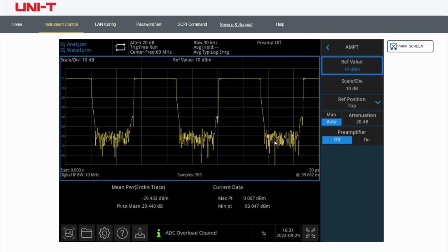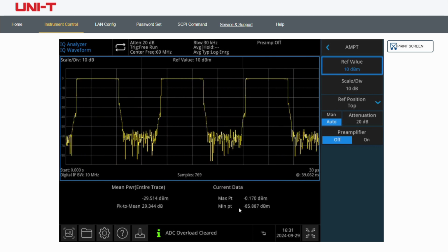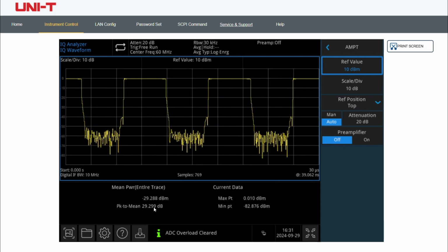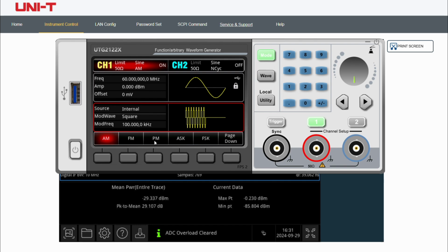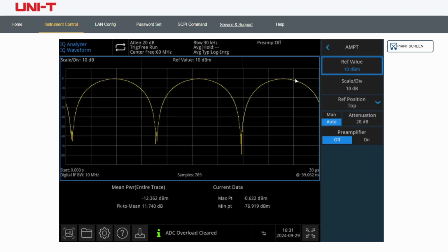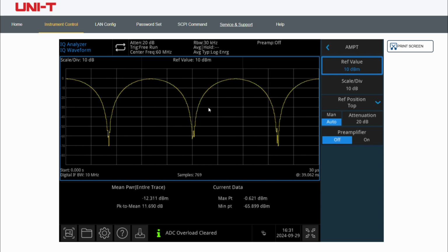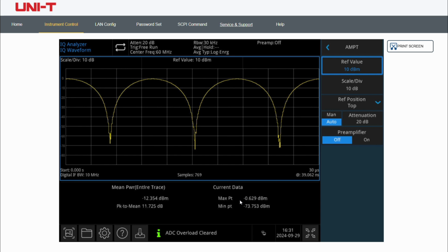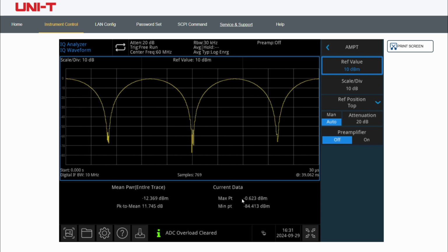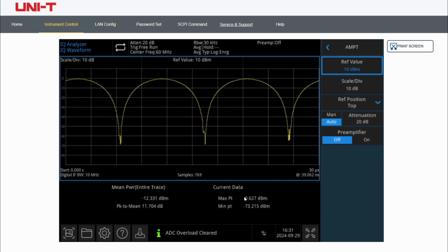So, what's the difference between the IQ waveform and the one just tested before? Earlier, we separated the I and Q paths, but now here we see it as a modulated wave. This is the baseband signal in digital communication. It looks like a square wave. We can export the data by IQ to analyze it. You can also see the I and the Q paths of the modulated wave. Especially in the measurement spectrum, you can see how much the phase difference between I and Q channels is.